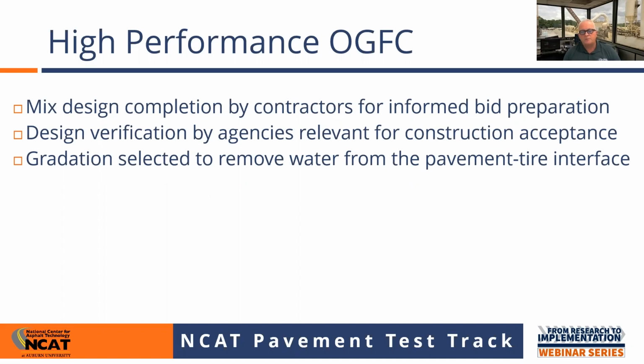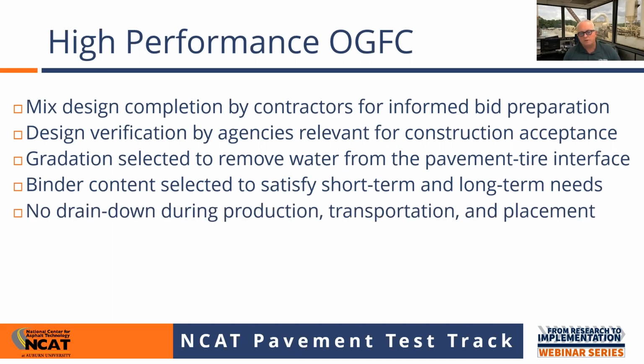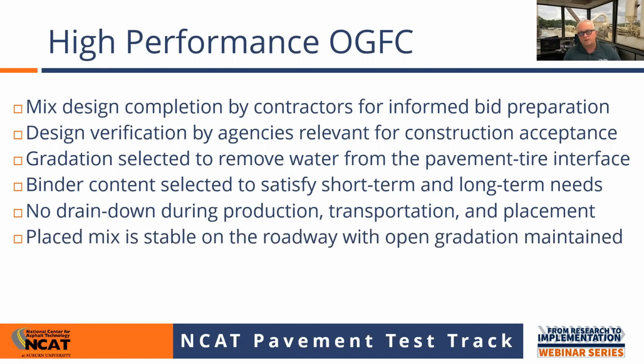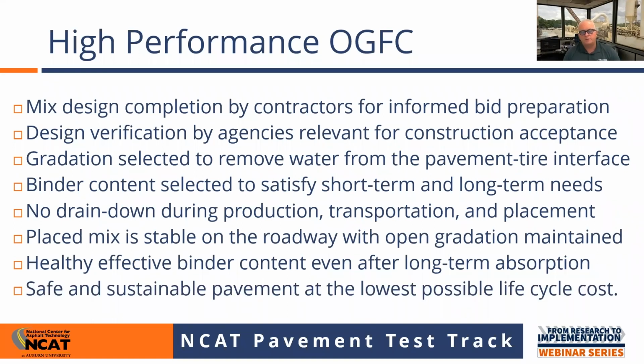We have a gradation in these mixes that is open so that water can flow out of the pavement tire interface and then off onto the shoulder. We have a binder content that satisfies our short-term and our long-term needs. So in the short term, we don't want drain down. We can't have so much binder that it drains down. When we place this mix on the roadway, it's got to be stable, and the gradation has to be open. We'll talk about that more as the webinar progresses. So we need a healthy, effective binder content even after long-term absorption.